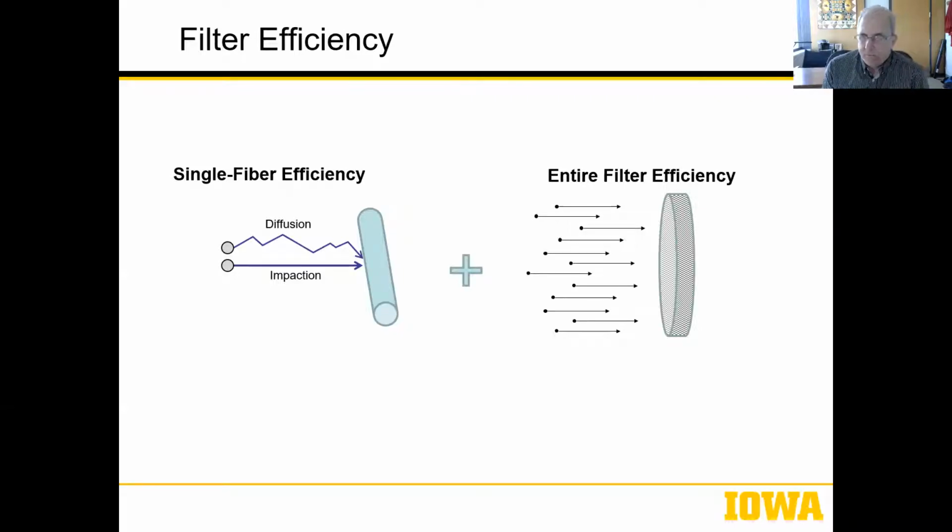Then you build up, in terms of modeling these things mathematically, or even physically, the filter itself is a mesh of different fibers of a certain thickness. And so you can move to trying to mimic or design filters of a certain thickness with strands of a certain size. And then, how porous are they? You've got to let some air through, right? They can't be just a rock wall.